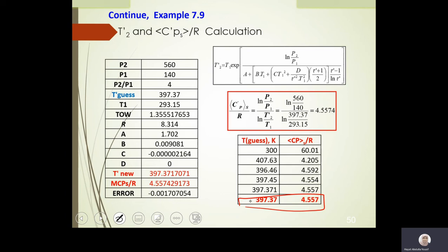Cp is constant, so the integration of dT over T is from T1 to T2, and here you have minus beta, and delta P is going to be V times the integration of dP, which is delta P. We can accept those two equations if the temperature change in the pump is very small, and this is normally the case with a pump, and if the properties are insensitive to change in pressure. That's why we consider those values constant and took them out of the integration.